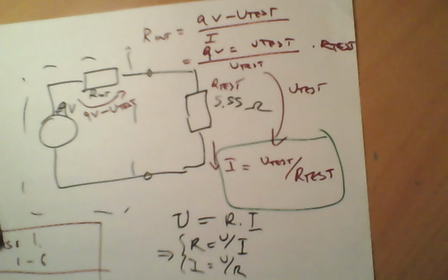With gigaohms, we don't have any current. With ohms, we have tens or hundreds of milliamps. With kiloohms, we have microamps. So to measure the current, you disconnect the connection and put the current meter in the middle of that connection.